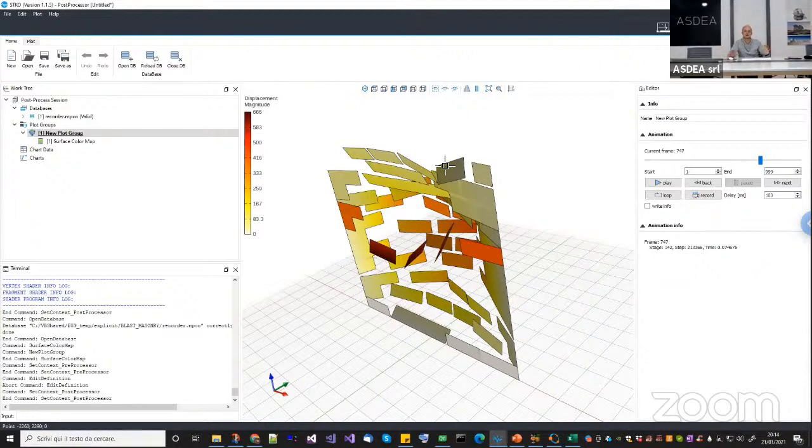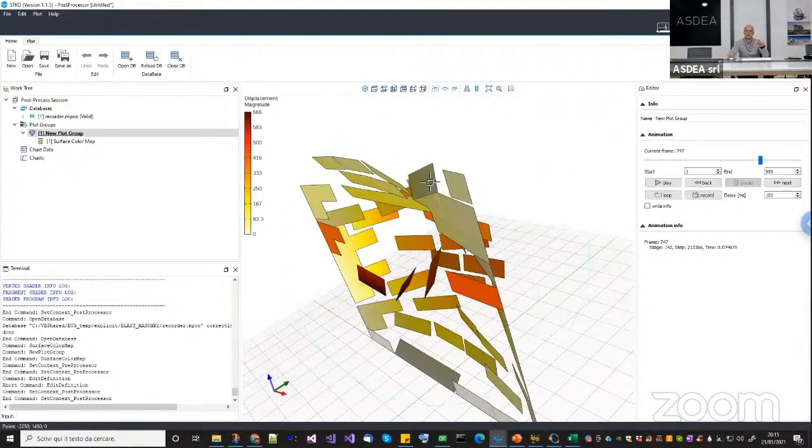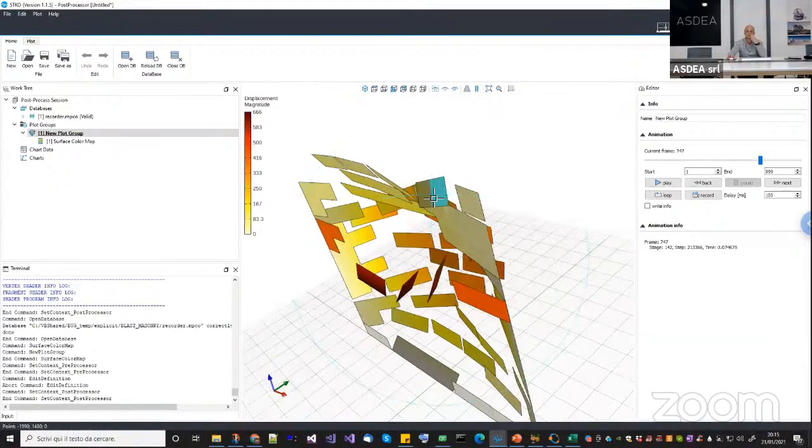So when an element is not attached, in dynamic analysis, it doesn't mean that it is unstable. It's simply dropping, okay? It is unstable if you do not assign a mass to it. So for example, let's say I forget to assign mass on this element. It will have a singular stiffness and 0 mass, so yes, it will be unstable, okay?